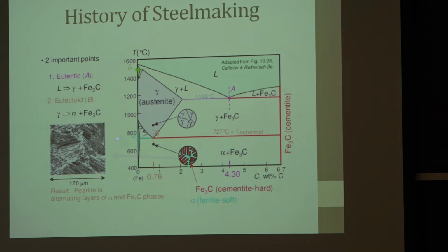And if you're only heating this thing up to 700 or below, you're going to form wrought iron, which is very low in carbon. That's the equilibrium. So you get very low carbon. It's almost pure iron, easy to work. Can't be hardened too much, but it's relatively easy to work.